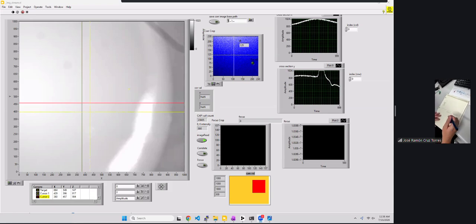In an ideal world where there's no backlash, and assuming linear behavior, you would get a perfect linear line that starts exactly at 0, 0. And you can think of each of these data points here as an independent test of moving it forwards and moving it backwards, and then checking the magnitude of this backwards move.